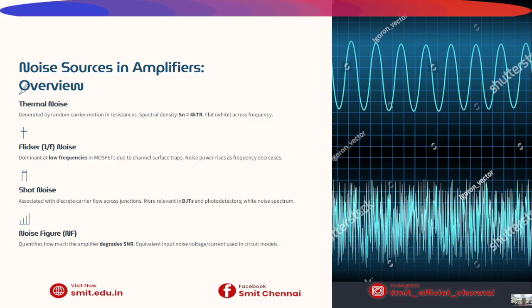Next, we see the noise sources in amplifiers. Noise is an unwanted electrical signal that affects amplifier performance. The first type is thermal noise. It is caused by random motion of charge carriers in resistive components. It exists across all frequencies and is often called white noise. The second type is flicker noise.